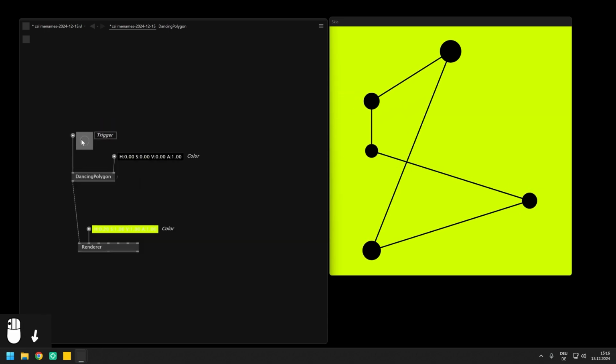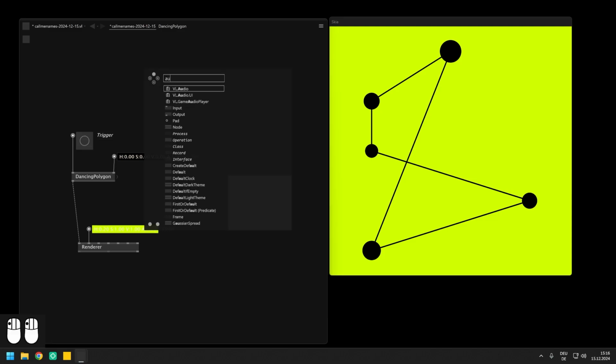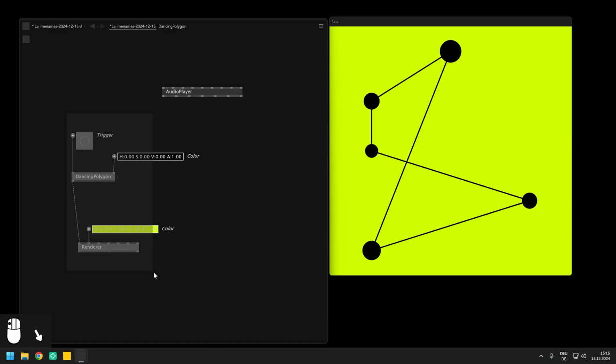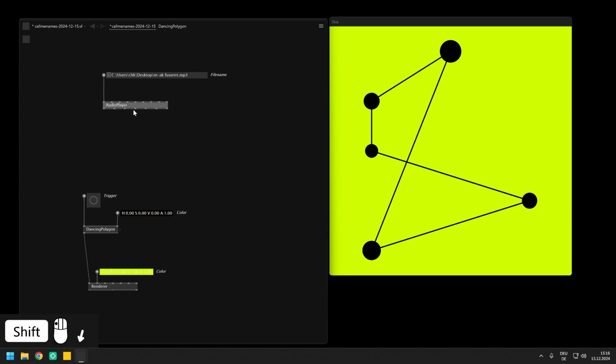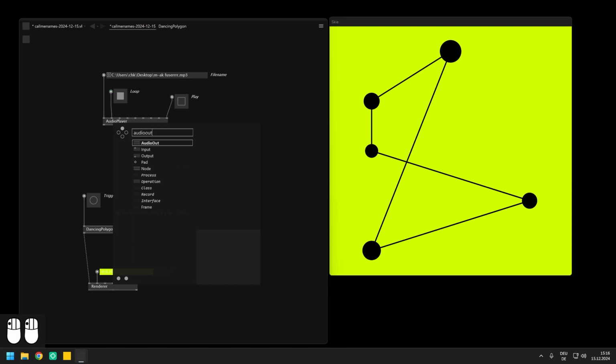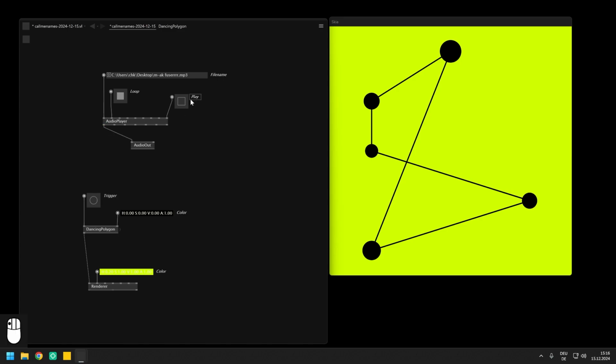We have finally come to a point at which we will set a reference to VL.Audio, as we are going to control the trigger and the colors using audio analysis methods. If you go to the link in the video description, you will find the track that I will use to follow along, so make sure to download it and then use an audio player with the loop and play inputs set to true, and an audio node to play it from vvvv. In case you don't hear anything, check out your audio input and output settings in the configuration extension, which you can find via the quad menu.